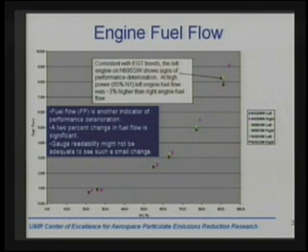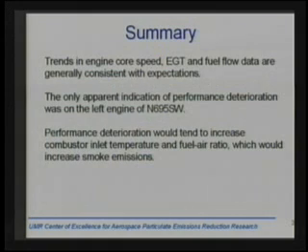And you can also plot fuel flow versus N1. And again, if you were to see a slight change in fuel flow, as much as, say, 2%, that might indicate deterioration. The problem we had here with this parameter in the field was that we don't have an instrumented engine in a test cell where a certification measurement might be going on, but we've got an engine on the wing. In the case of the 737-300s, the fuel flow was indicated in the cockpit with a mechanical gauge. For the 700s, it was actually a far more precise measurement that was electronically recorded by the aircraft. So again, it would be hard to see in the nature of the experiments, particularly with the 737-300s here, whether this was an issue. But again, generally speaking, we'd argue that we've got a clean bill of health.